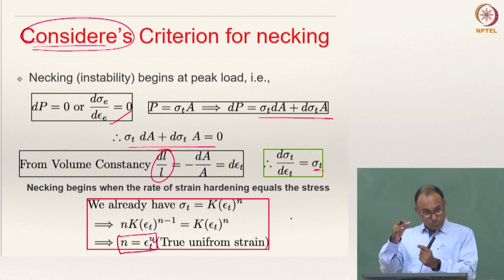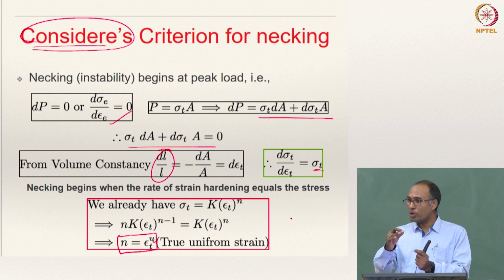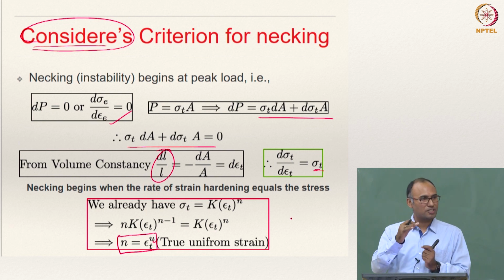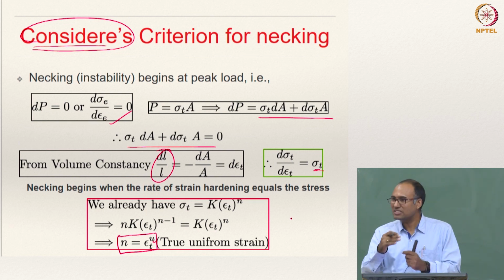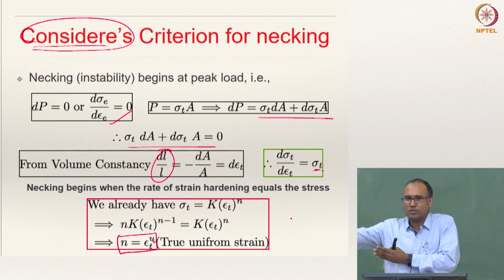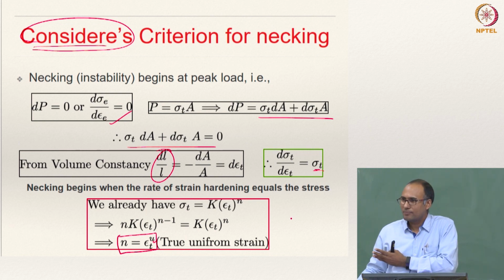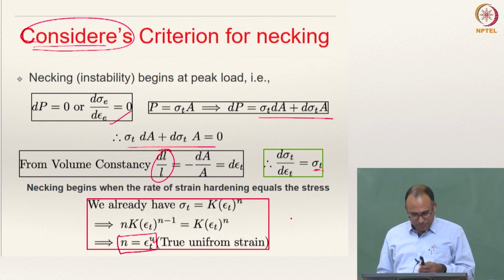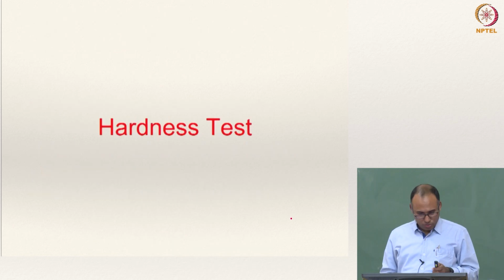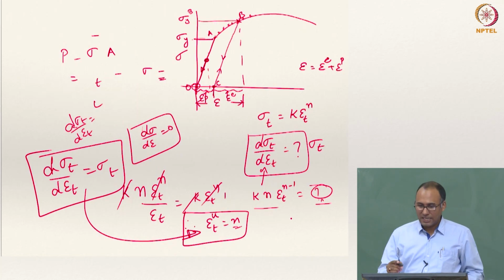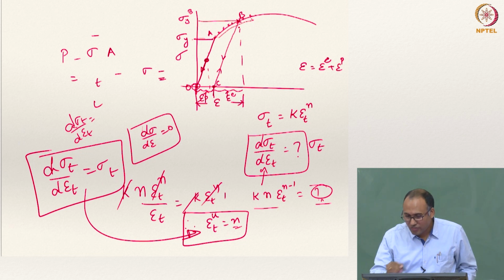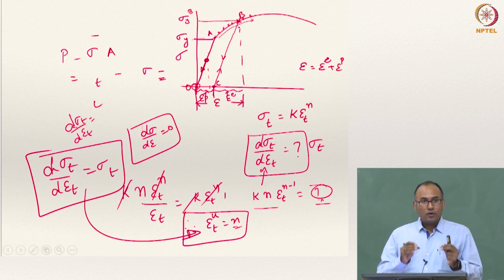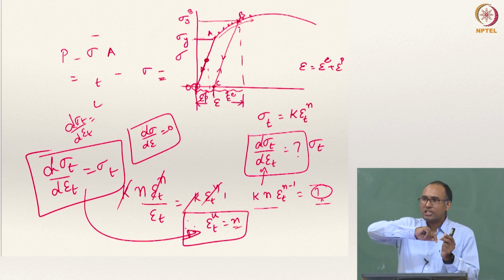So if you take that specimen, is it going to be more brittle compared to the virgin material or not? You will find that it is getting more and more brittle because it is actually going towards its failure point, right? So the important thing to realize is that when you are doing plastic deformation to a material, from each and every point you are actually transforming your material.